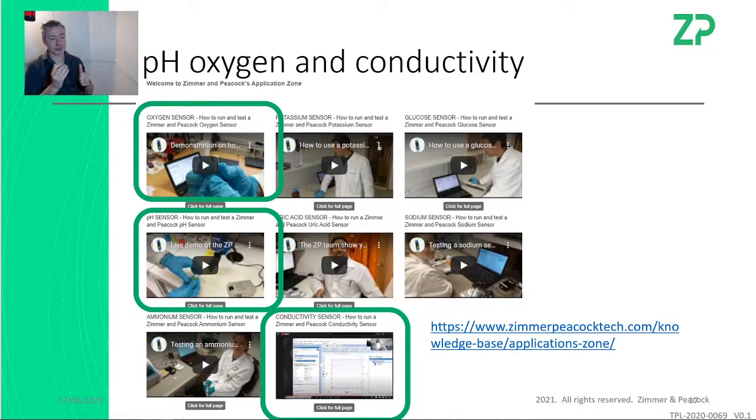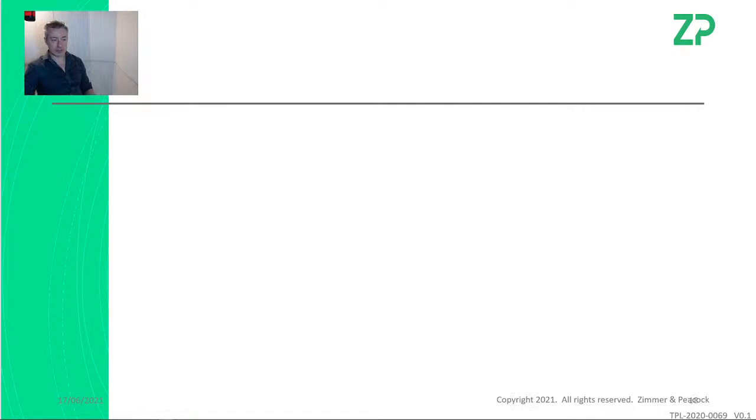But the short answer is they're not coming in that sort of standard 4 to 20 milliamp or that 0 to 10 volts or that 0 to 5 volts. I do understand the question, but the answer is no. They're giving out more of a sort of R&D signal rather than a sort of signal that the industry would be directly looking for. It's not that we couldn't do the conversion or do an adapter between the two. It's just we haven't, is the quick answer.